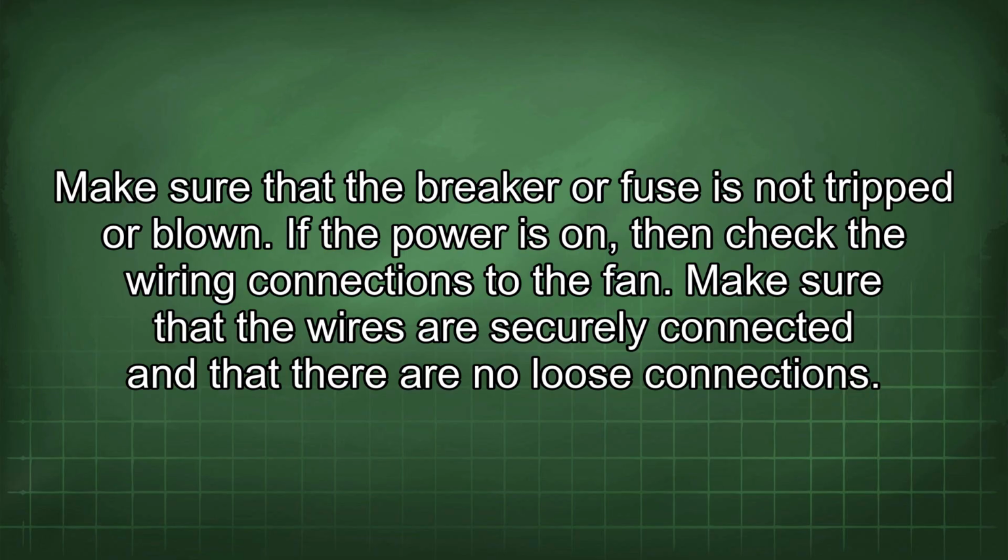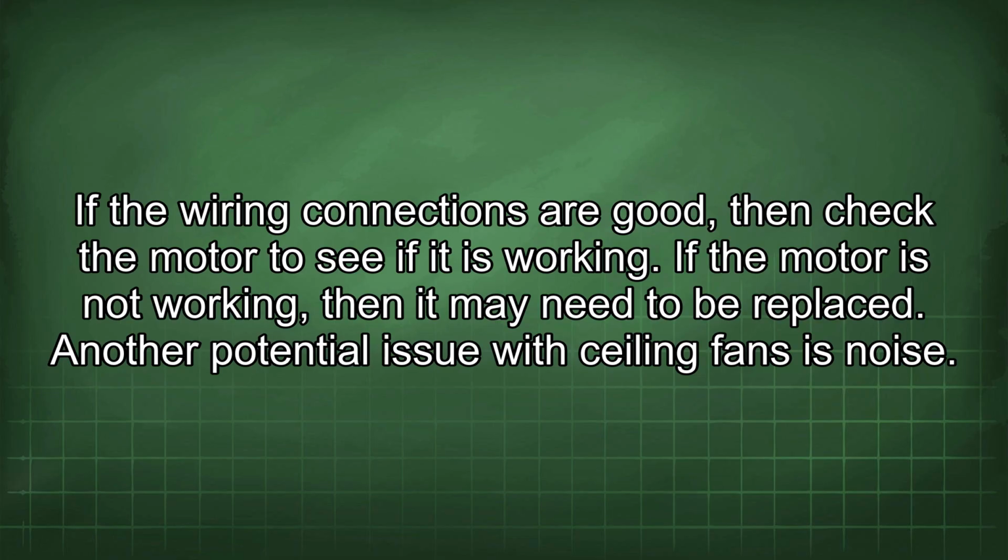If the power is on, then check the wiring connections to the fan. Make sure that the wires are securely connected and that there are no loose connections. If the wiring connections are good, then check the motor to see if it is working. If the motor is not working, then it may need to be replaced.